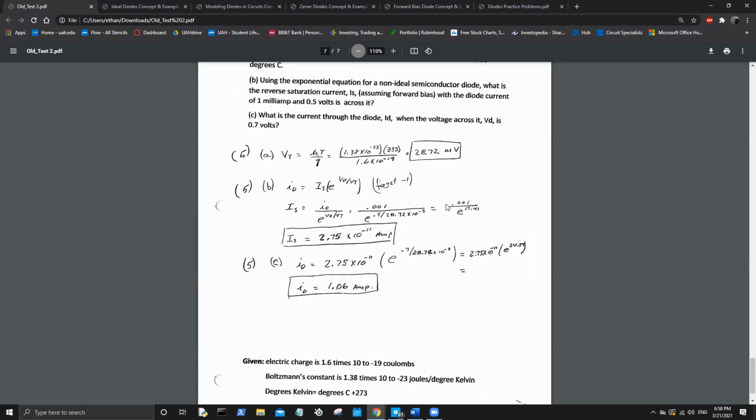The answer is because 0.5 volts isn't enough to start up the diode into conducting phase. Because here, in C, all he gives you is that it's 0.7 volts, and you get to start transmitting. Look, IS is almost picoamps. That's nothing. That isn't conducting anything. So fundamentally, he just gives us some current value that's acceptable and 0.5 volts. This could have just as easily been 0.1 milliamps and 0.2 volts. All it needs to be is data points that can compute IS to some disgustingly tiny amount of current.